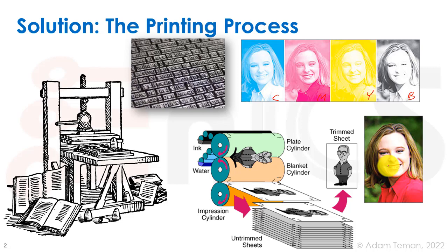It's still one single step that produces one part, like one blue or one magenta part of the process. And then we run our wafer through the process, and we get the billion or trillion transistors, or we get the single transistor, but it's only a single time step that it takes to do it. And that's what very large scale integration is. That's why it doesn't cost us extra time linearly according to the number of transistors or devices we want to print, but it takes a certain single amount of time, and we can print whatever number we are able to print at that time, and that is what enables us to integrate so many devices on the same substrate.